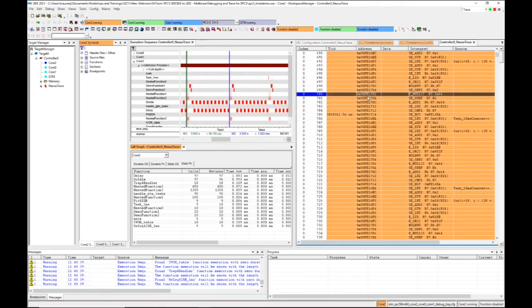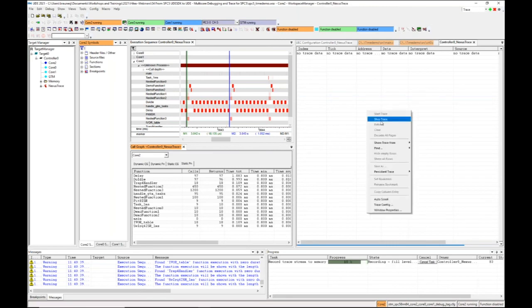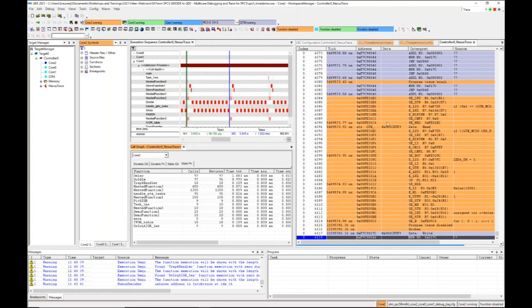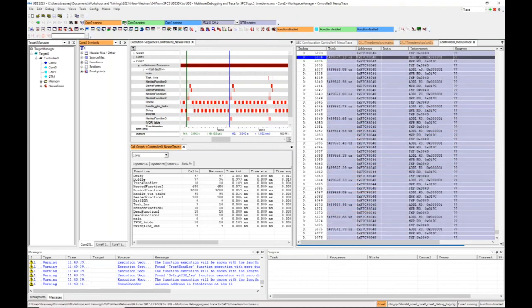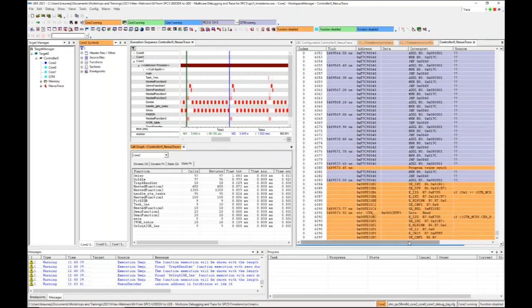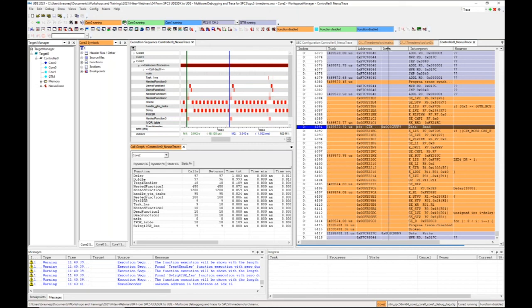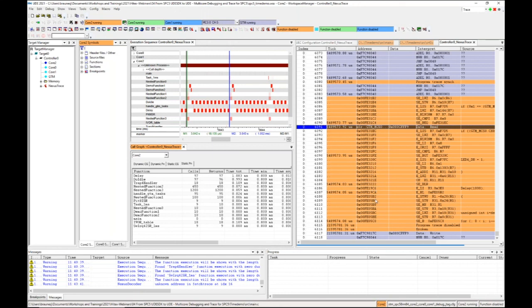So everything is running, and then I can start the trace recording. And in this case, I'd need to stop it manually because there's no stop condition here. And go then to the bottom, and here I see in the bluish part, this is the executed GTM code. Here this question mark indicates no source code is available, and this orange one is the code of the core 2. And we see here we have a data access which is sometimes not in the right order because of some FIFOs that we have in the trace system. That is also important to know, that you have to look a little bit in a wider range to find some correlations here.